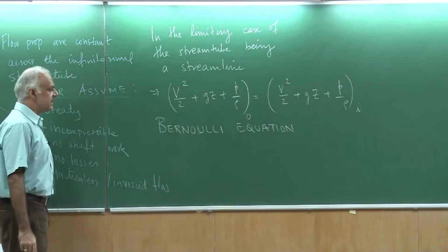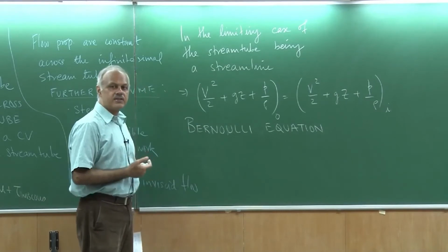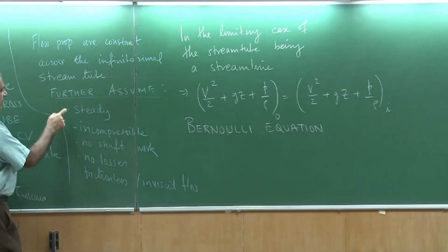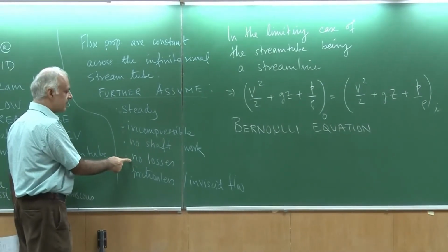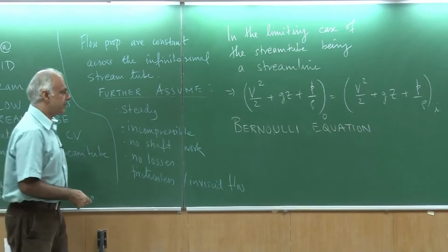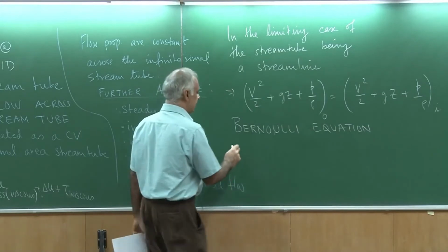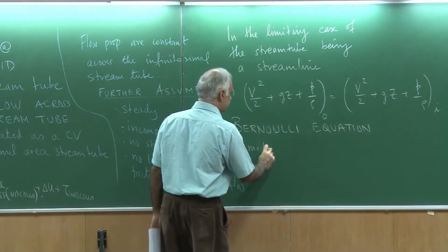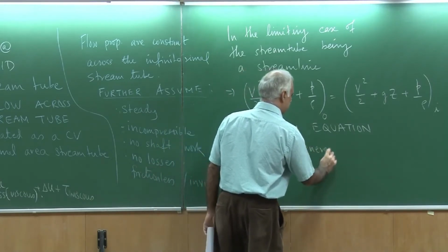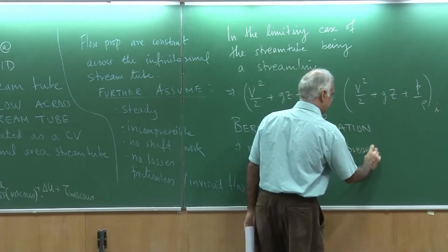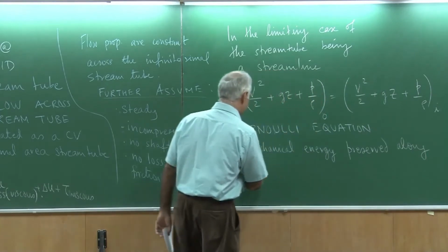So, the Bernoulli equation says that along a streamline for a steady incompressible, inviscid flow which has no losses and which has no shaft work, I have the preservation of the mechanical energy. So, this implies mechanical energy is preserved along a streamline.